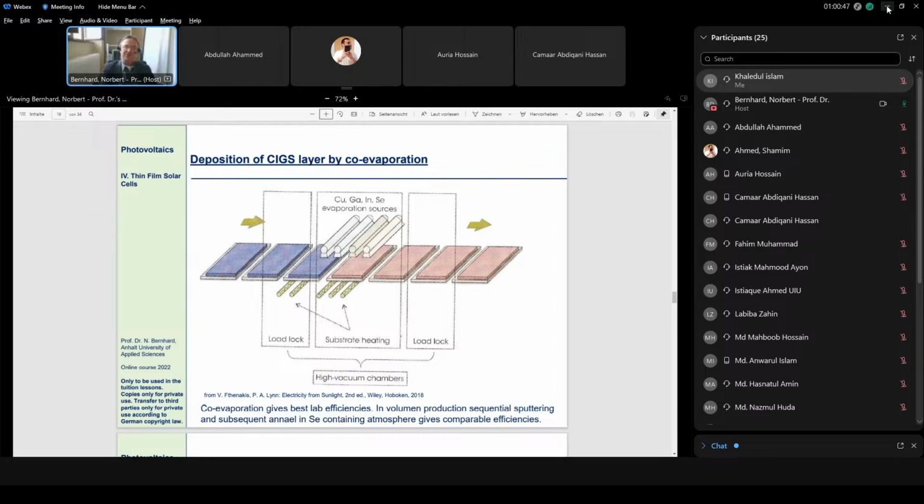The cadmium telluride makes a phase transition from the solid to the gaseous state. That means a sublimation. And the carrier gas takes it with it and brings it here to the surface of the heated material, and here a cadmium telluride layer is deposited. And you see you have a continuous feed actuator such that you have a continuous supply of this cadmium telluride which is sublimated.